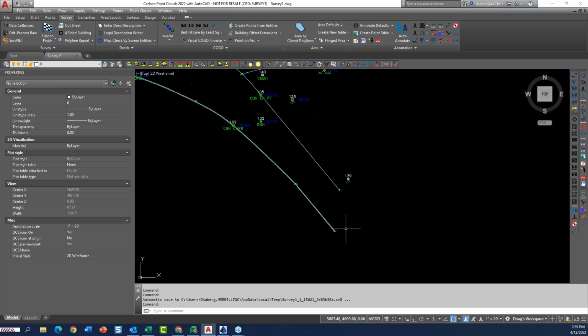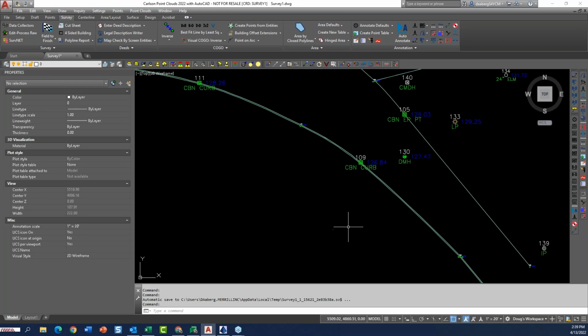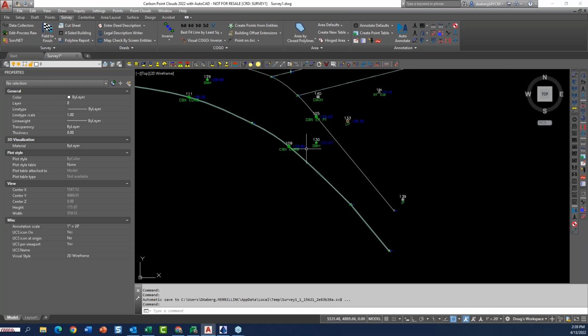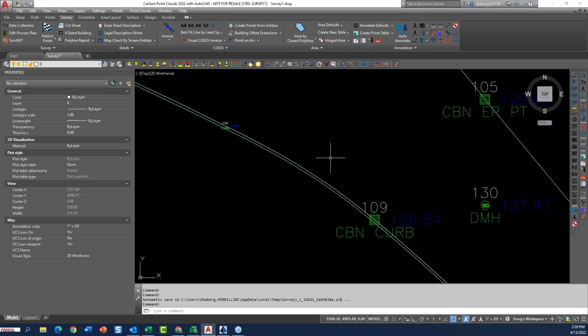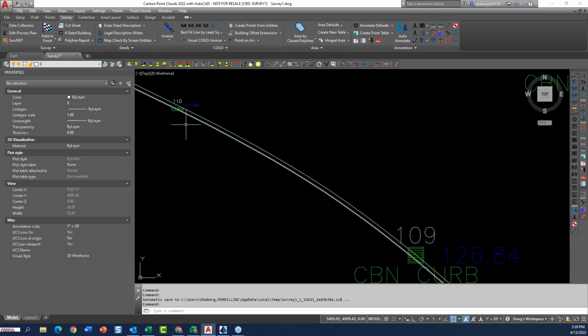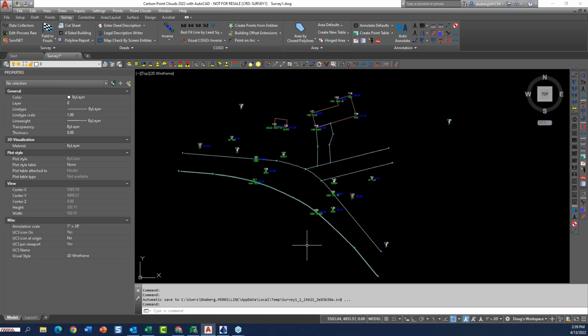And if the curb, again, is a pretty consistent curb, especially like on as-builts, it's an incredibly good tool because you can put that in once, and all your curb lines are drawn. It saves you from shooting that back of curb shot. So it saves a ton of line work.